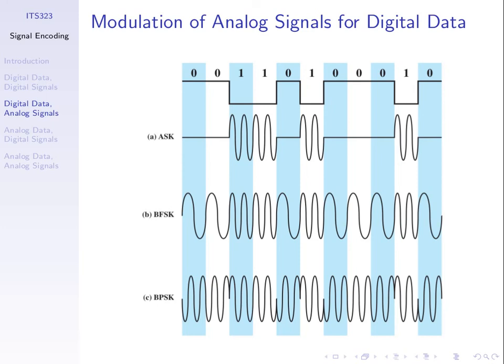So we change the frequency of our output analog signal depending upon the input bit. And what the receiver does, as they receive this signal, they measure that characteristic. If they can measure and determine, okay, over this period, what is the frequency? And if they determine it's a low level, then they know it's bit 0. If it's a higher frequency, a bit 1. What are the exact values? What are the exact frequencies? They are defined in the different systems. So whether it's 1 hertz, 1 megahertz, or whatever, that would be defined in advance.